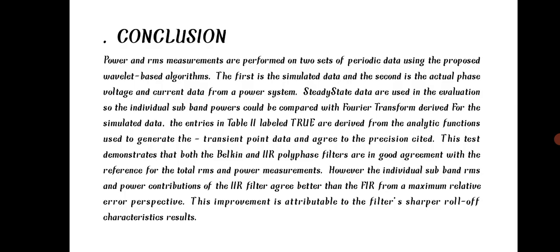Conclusion. The power and RMS measurements are performed with two sets of periodic data using the proposed wavelet-based algorithms. First, the simulated data, and second, the actual phase voltage and current data from the power system. Under steady state, the individual subband powers could be compared with the Fourier transform.